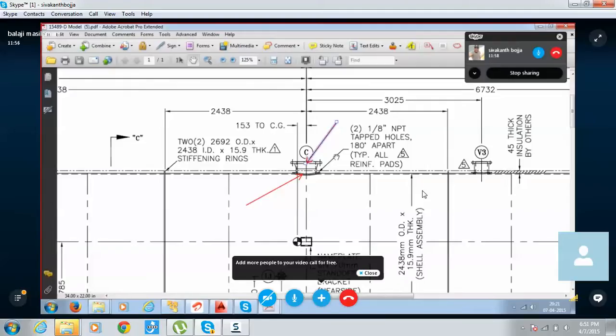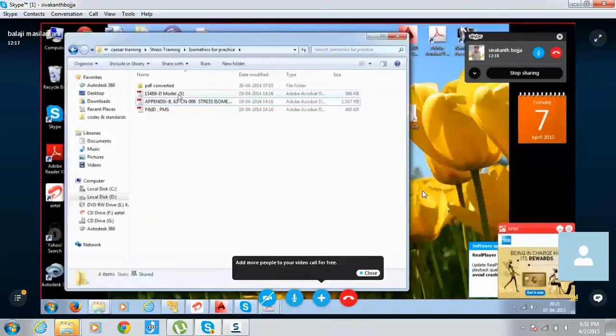After that you have to give the supports as per the feasibility, or as given in the isometric, based on the availability of steel. After that you have to come to the equipment. This is the procedure we have to follow. Node numbers you can give anything, I mean 10, 20, 30 like that, a 10 series, or 10, 30, 50 like a 20 series, or a 5 series. Better you go for a 20 series. 10 is also standard.